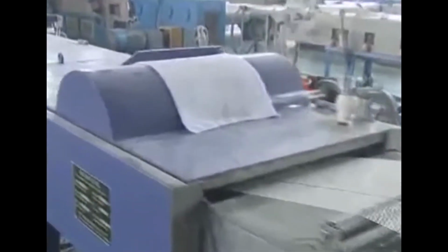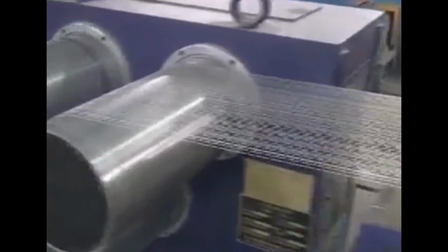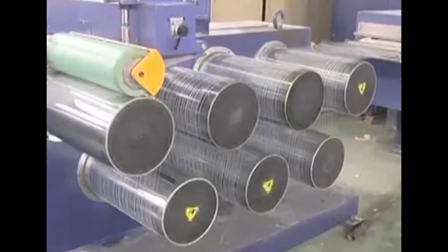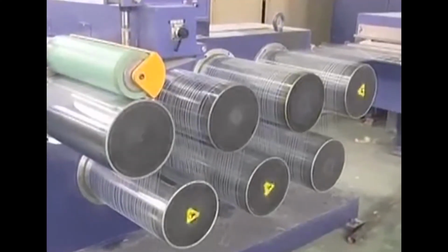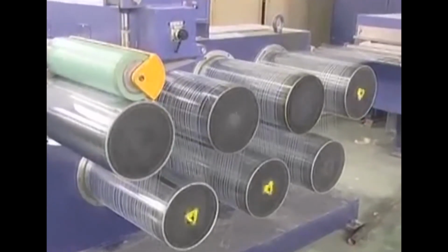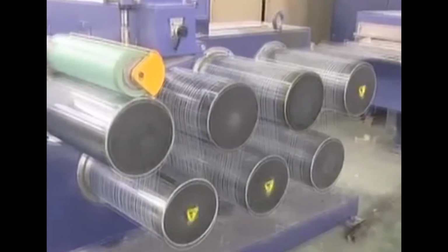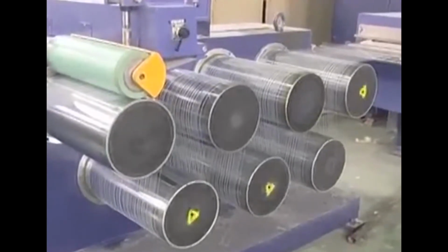And so, after melt spinning, mostly these materials are cold drawn in order to improve the fineness as well as the alignment of these molecular chains to the fiber axis. Usually, it contains again two sets of rollers, with a difference in speed, and the second one always revolves at a higher speed than the first one. And usually here it is maybe around 4 times higher speed than the first roller.